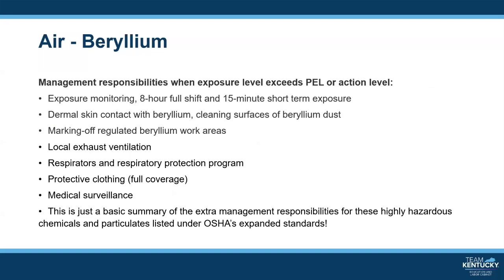There would be a requirement for marking off regulated beryllium work areas. It could require local exhaust ventilation. It could require respirators and a respiratory protection program. It may require protective clothing, full coverage. It could require medical surveillance of the employees. This is just a basic summary of the extra management responsibilities for these highly hazardous chemicals and particulates under OSHA's expanded standards.